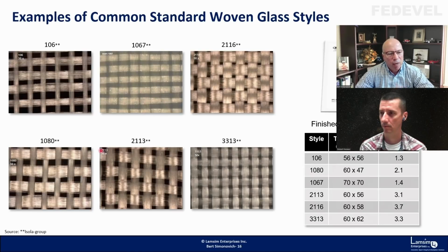I can talk about fiber weave effect in it. But the big thing to take away from this picture is there are different glass styles, different weave patterns, different thicknesses, and different pitches, distances between these things. So how is this important? Yes, it's important for fiber weave effect, actually.